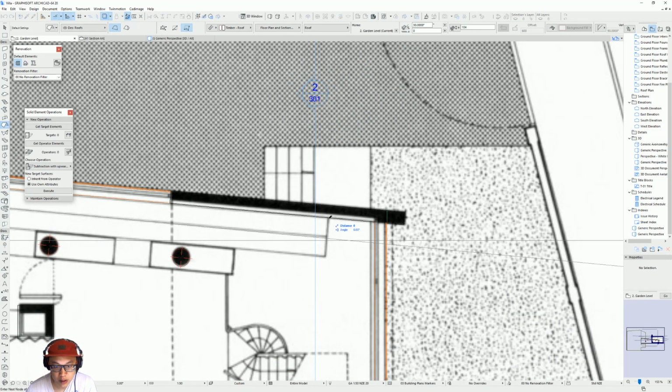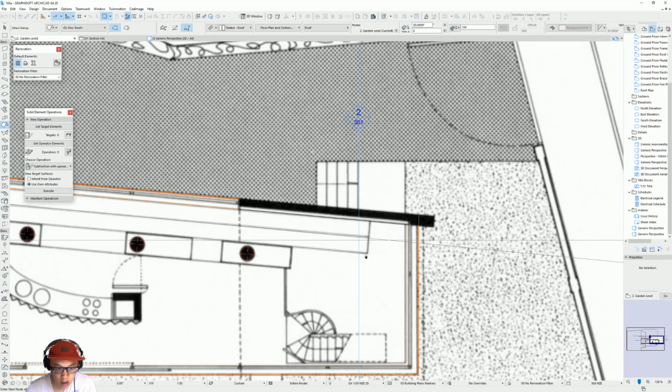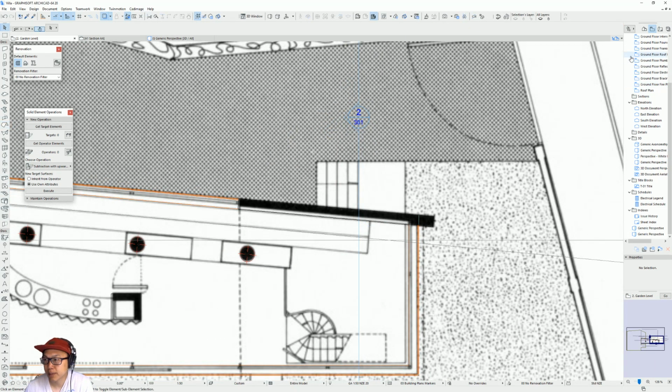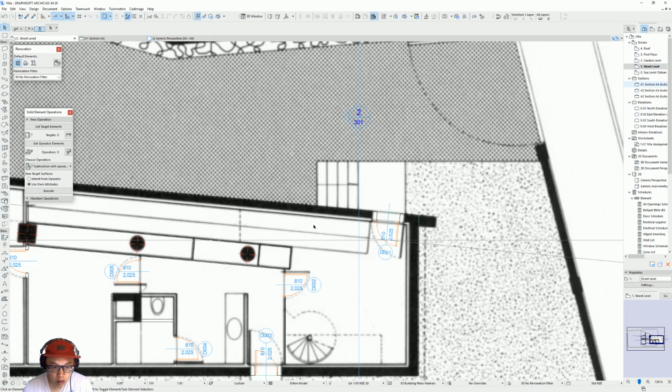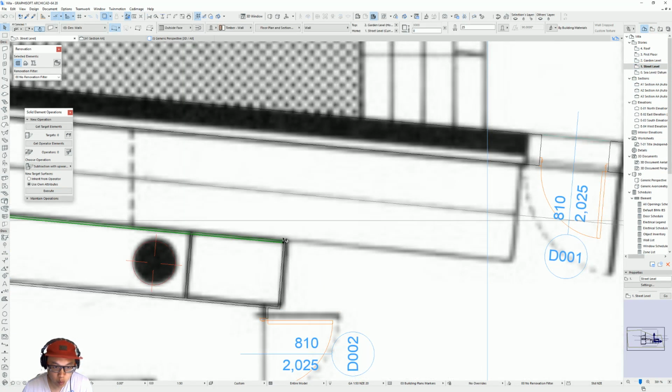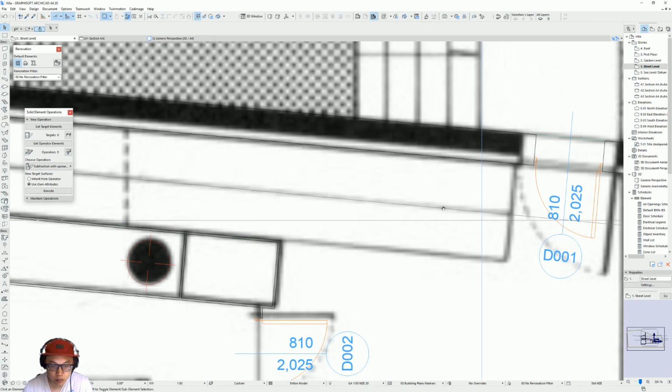And I'm going to use this as my starting point here. Make sure you go over the guidelines, so that's a 90-degree angle. And oh wait, if we go to our street level, we'd already have the wall there, so we get that distance. So what I'm going to do is click that, and create a guideline by pressing Shift and the tilde.